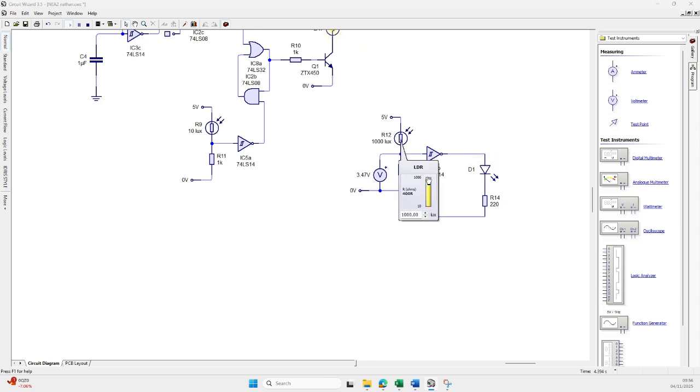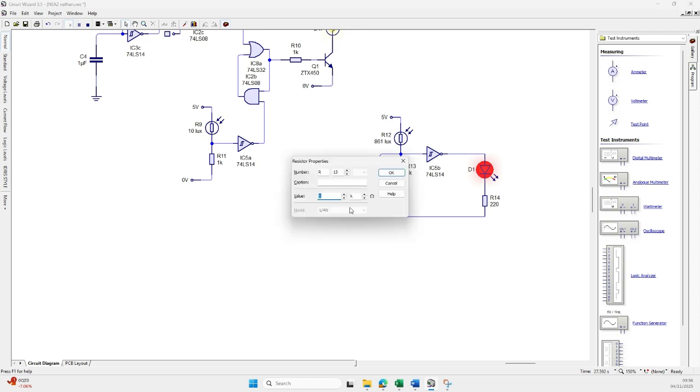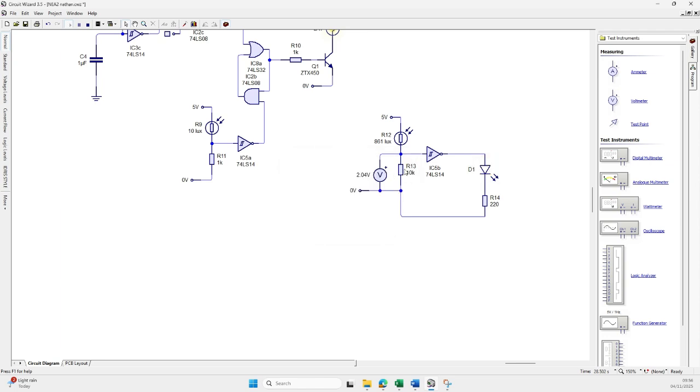Okay, so you can see it's quite, maybe we might need to change that resistor value, but you can kind of see the idea of when I decrease the light level on here, it's changing it, and then you can see the LED is switched there. I've got about 600 millivolts at that switching voltage. You might want to change that, to be honest, but you don't have to. You can just have that as your results. It doesn't matter. There you go.